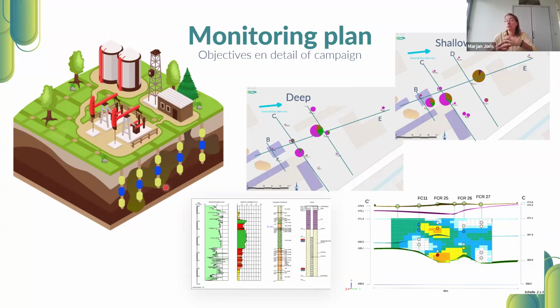Of course, if you need more detail and you want to have a more average evaluation of the contamination present and spreading, then you will have to measure at more depths in the different layers, for example, in high and low concentration areas. Let me show this with this example at the right.